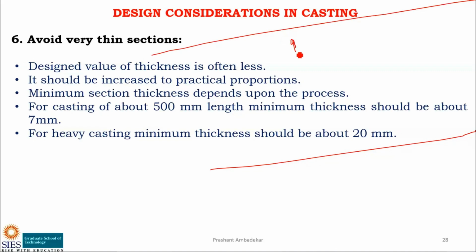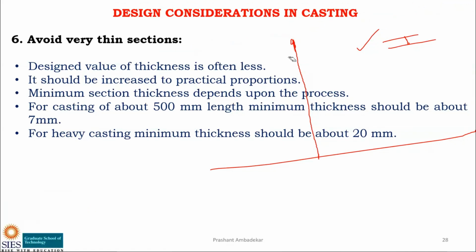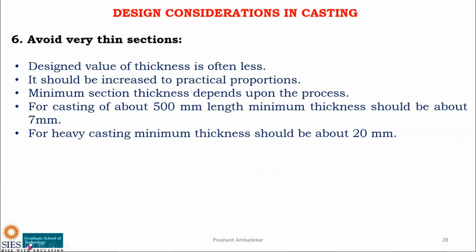If suppose crack is initiated here, it will take time to propagate and to reach the surface, and then it fails into two parts. But if it is a thin section like this, crack will easily get propagated and it will fail quickly. So in case the section is thin, then you have to change the dimension. Change the dimension मतलब देखो, after designing you are getting some dimension. Okay, that is correct, and that dimension says that the material will not fail.